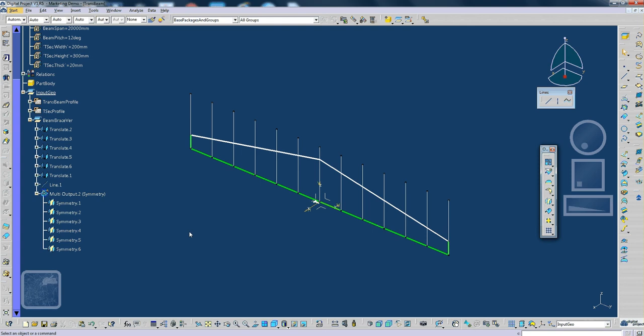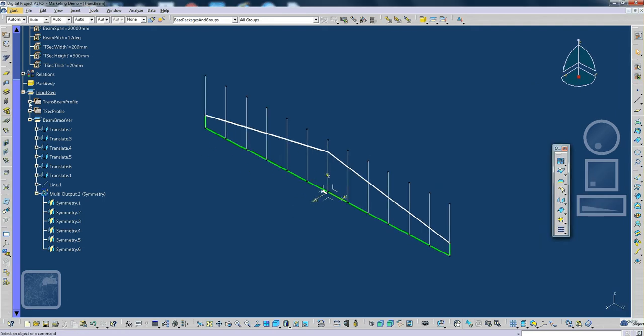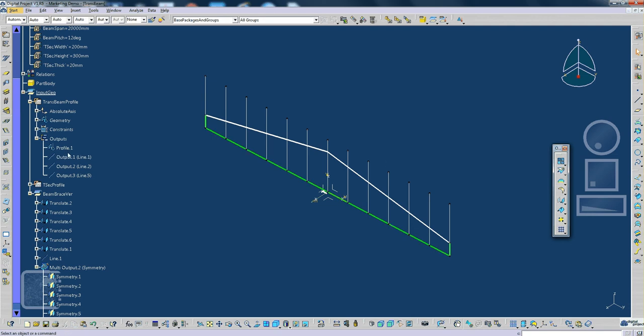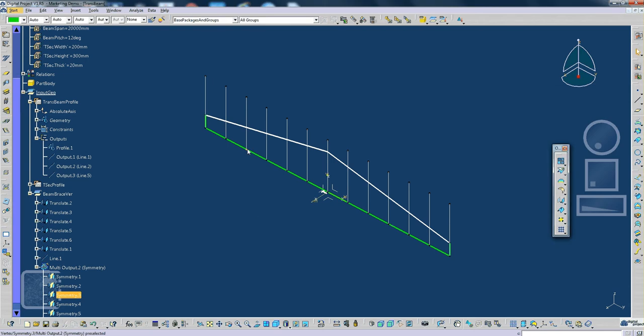Okay. Now we're gonna change to the architectural workbench. Alright, so first of all, we'll make the periphery beam T section. So pick this line and also these 3 lines, and get this multi-support beam. Sorry, I shouldn't select this one. I just pick this, and that, because that will have a different support plane. So I pick 1, 2, 3. The one shows in orange color with multi-support beam.